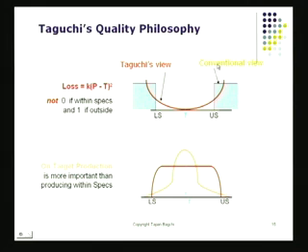The first thing, of course, is the conventional view of quality, which just says anything that is off spec suddenly becomes bad. Once I land up in the area that is off spec, outside spec limits, things suddenly become bad. Taguchi said that is not true. The moment you deviate from the target, society is incurring a loss, and you're basically inflicting a loss on society. And that will take place even if you move away just a little bit from this. And the amount of that loss can be given by this loss function.